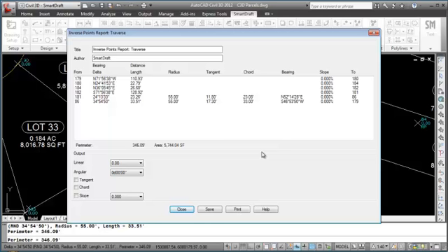In the report dialog, you can enter a report name, the author's name. It shows all segments you have inversed, a perimeter value, an area value, because this is a closed inverse. If it was open, this would not be there. For the report, you can change the linear and angular precision different than what was at the display. So here I just changed it to 3 decimal, back to 2. Include or exclude the tangent and chord information in the actual report.